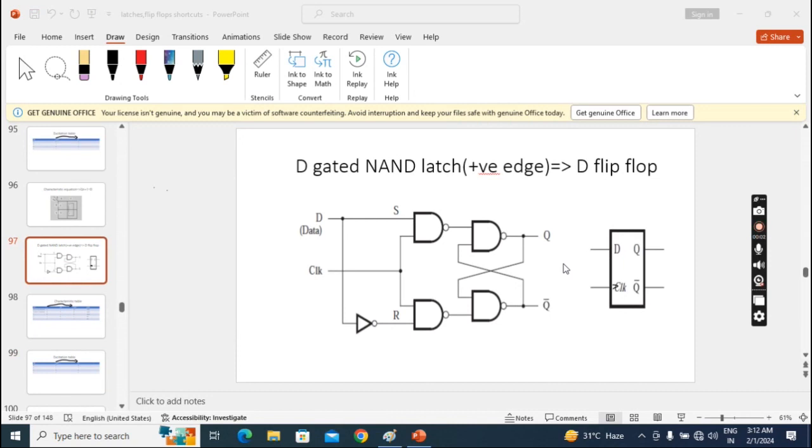In this lecture, we'll discuss the necessity of the D flip-flop. We get the D flip-flop from SR only by interconnecting JK and connecting one inverter at a suitable place. This D flip-flop was ultimately developed for the implementation of shift registers. In shift registers, the input and output data should be the same. In that case, only the D flip-flop is suitable. No other flip-flop will produce the same output as input.